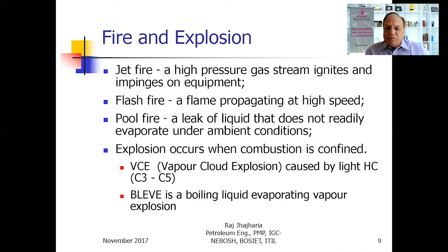BLEVE is another type of explosion, and it's called boiling liquid expanding vapor explosion. How it happens, it's a combination of, let's say, jet fire and a tank. Suppose there is a tank which contains propane, or let's say LPG, or any hydrocarbon in a liquid form, and there is a neighboring jet fire.